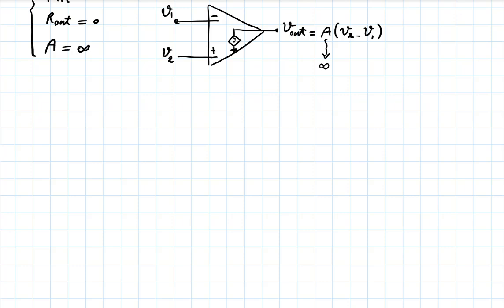In most cases, that's what the op-amp does for you. In most circuits that you will deal with, all the op-amp does is take two nodes and make sure there is no voltage difference between them. Now, that might sound very weird because it sounds as though I'm doing something that I shouldn't. I'm enforcing something. So we'll see it in action. But let me write this down before we forget, and then we'll see what it means.